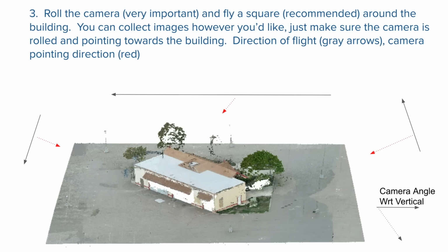If everything goes well, if you don't bang your drone in a truck or have a crash landing, or if everything's going without a hitch, conventionally with photogrammetry, people are typically calibrating once a year. Now, with a drone platform, it's a little bit less robust than maybe an airplane system.